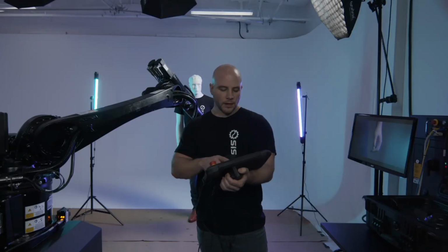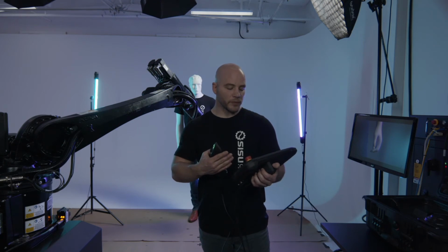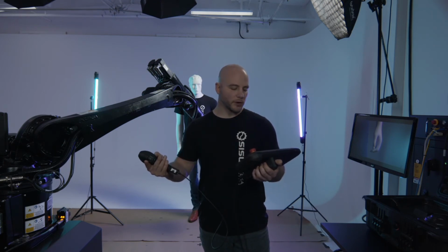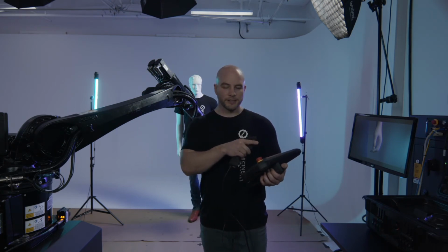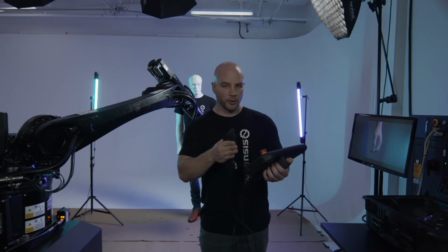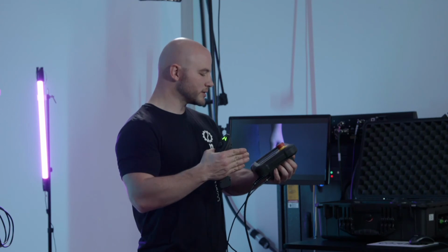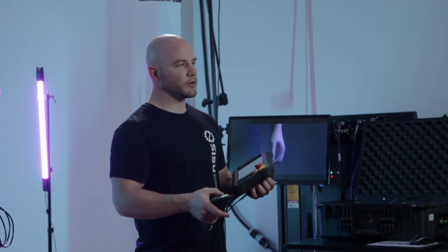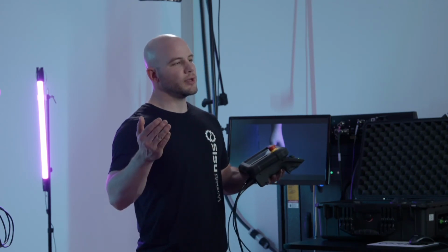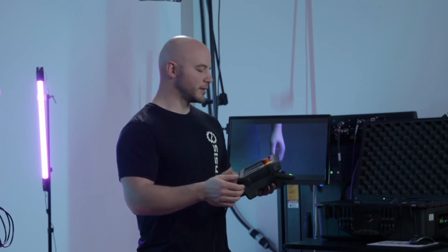So you can do this not only on one keyframe, but say I had 10 keyframes in this program, I can turn on normalized speed for all of those middle points, not the first and last, but all of the middle ones, and it's going to give you the result you're looking for, a nice, smooth, normalized, or constant speed.